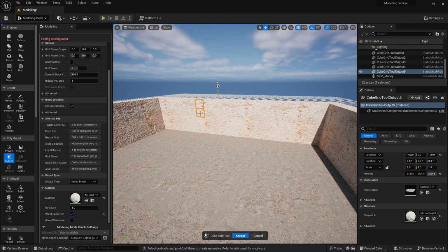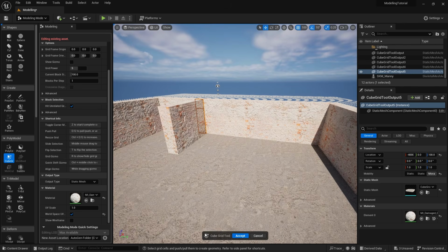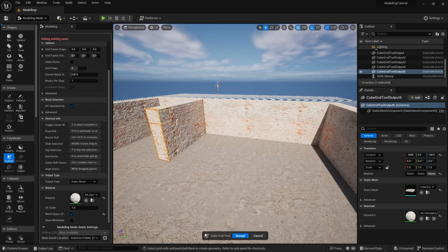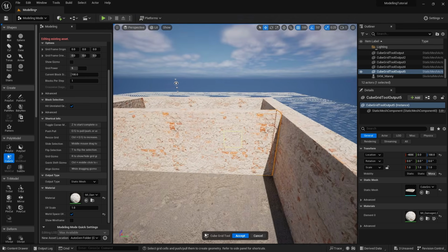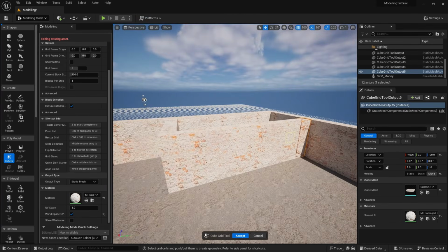So I'm selecting these floor blocks of this wall, and I'll show you a different way here. So obviously you can press E to extrude, but what you can also do is hold the control key down on the keyboard and then use your left mouse to drag out the content. So this is kind of a more interactive approach. So drag it out 4 or 5 meters, and then I'm going to select this part of the wall here, these 4 meters, and then use Control to drag out to the other side, like that. So now we've created a room.